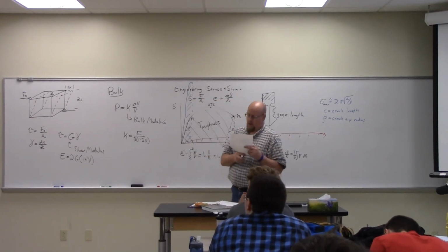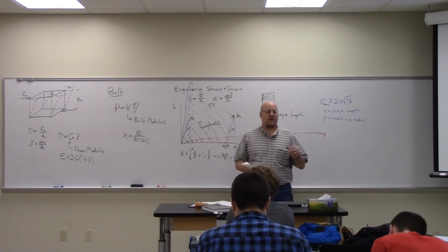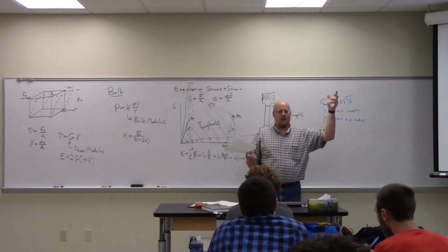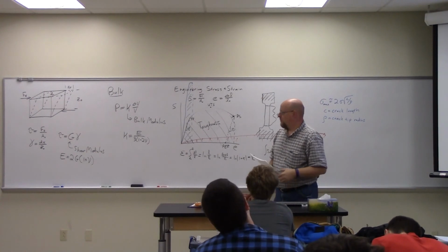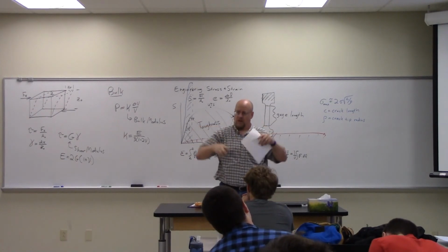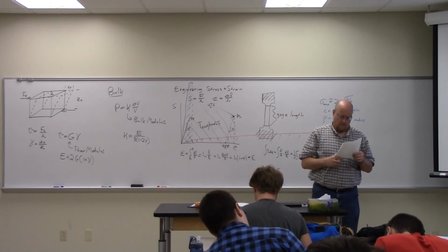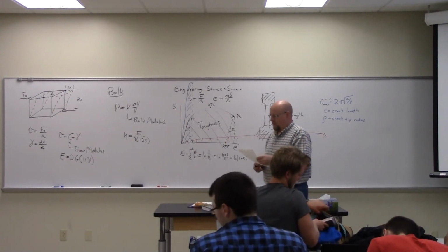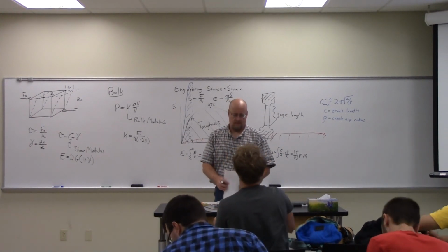There's a couple other characteristics that your book lists. A modulus of rupture, which is used when you can't pull something in tension. If I want to check the tensile properties of a brick, I can't load it in my tensile machine and pull on it. That's not really going to do it. So there's a modulus of rupture test where basically you support it on 2 points and push down in the middle and see how it breaks there. And then there's a flexural modulus that results from that. But I'll refer you to the book to read those things. Any questions?